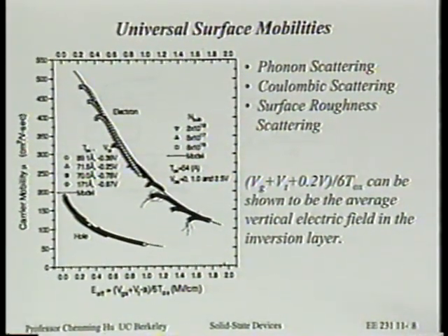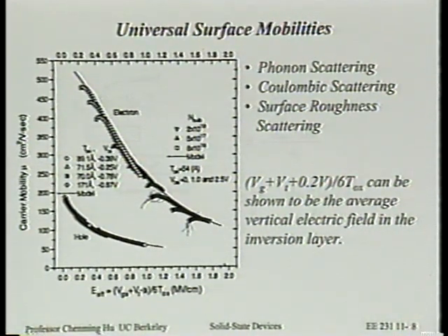There are several possibilities. Perhaps we simply have fewer interface traps in the PMOS than NMOS. It's possible. Maybe because of the difference in effective mass between electrons and holes, the location of the holes and electrons is slightly different, or they respond slightly differently to Coulombic scattering versus phonon scattering. And Coulombic scattering, we know, is responsible for the 1/f noise. Remember, when we talked about 1/f noise, it is due to Coulombic scattering. That's mobility fluctuation. When the charge goes into the interface trap, it becomes a scattering center. Is that right?